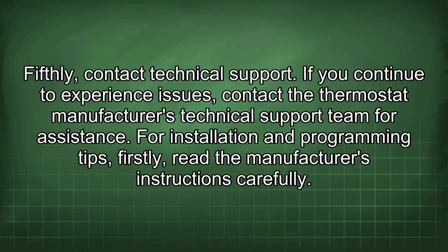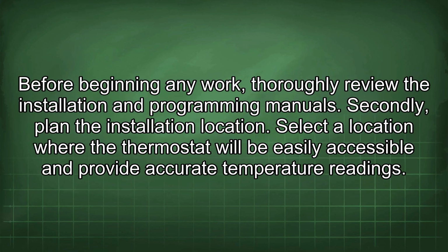For installation and programming tips, firstly, read the manufacturer's instructions carefully. Before beginning any work, thoroughly review the installation and programming manuals. Secondly, plan the installation location. Select a location where the thermostat will be easily accessible and provide accurate temperature readings.